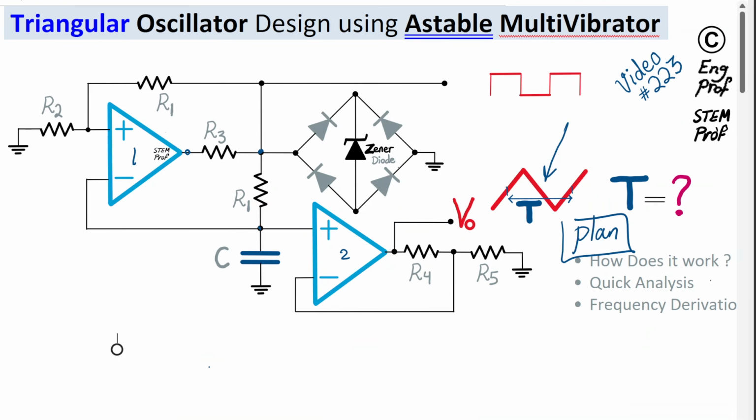Here's the analysis. At the output of the circuit, we are saying it generates this triangular waveform. As you can see, this second op-amp, I really recommend that we use standard good op-amps from TI or Analog Devices that are dual supply. We need dual supply in this case, let's say plus minus 15 volt, not higher. That's the level that we want to have for these op-amps. So I make the assumption that a proper dual supply is applied, let's say plus minus 15 volt tops or plus minus 13 volt in this example.